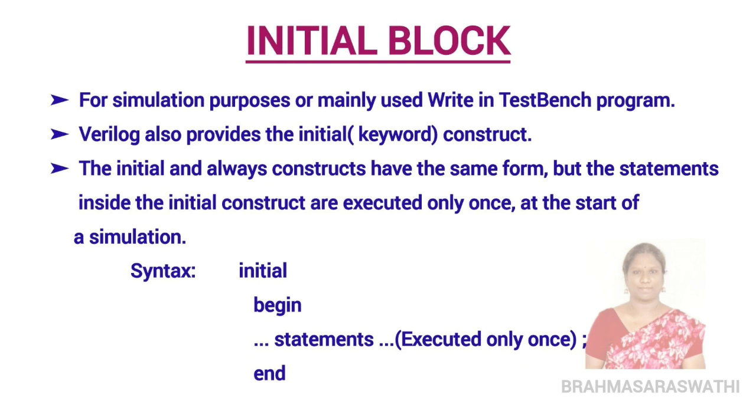You see the first point. For simulation purposes, it is mainly used and written in test bench programs. This means the initial block is written only in test bench programs. The second point is Verilog also provides the initial construct. This means if you observe the always block, the always keyword is used to write it. Here, in the initial block, you use the initial keyword.